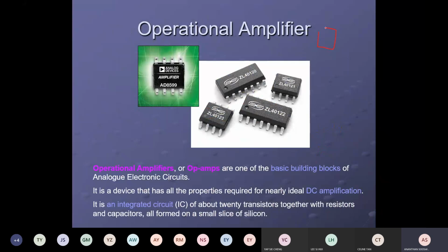And the first department is what? Sensing device. The second department is the operational unit. The third is the output. So we're done with the sensing. 4 types of sensing are there: LDR, thermistor, what is that? Piezoelectric transducer. Then the fourth one is strain gauge. LDR senses light intensity, thermistor senses temperature, piezoelectric senses pressure, and strain gauge senses strain. Strain. How big is the strain?